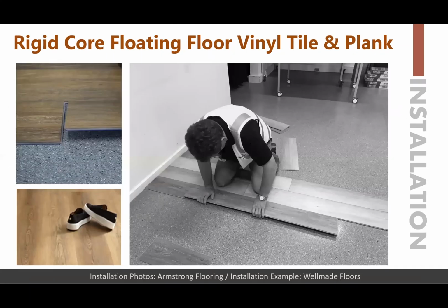There's not much of an installation method difference between SPC and WPC LVT, but there's an important distinction between what the installations are and how they are applied. For instance, an intended click-together LVT is similar for SPC and WPC, and if some adhesive is used, the installation should not fully adhere a floating floor. Typically, loose lay is intended not to have adhesive, but some installations may require a partial adherence in a commercial application. But again, if full adherence is required, the product should be changed to use a fully adhered installation. A non-click vinyl plank for a commercial installation does not click together, as the edges are butted.